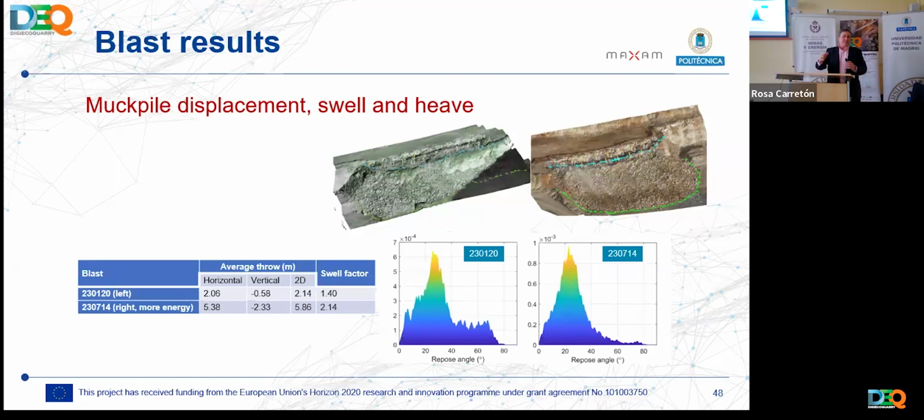Sometimes you may need to drill 5 by 6 meters, sometimes 5.5 by 6.5 meters. No, it doesn't matter. You always drill the same. Just use different energy of the explosive, and you can get different results.